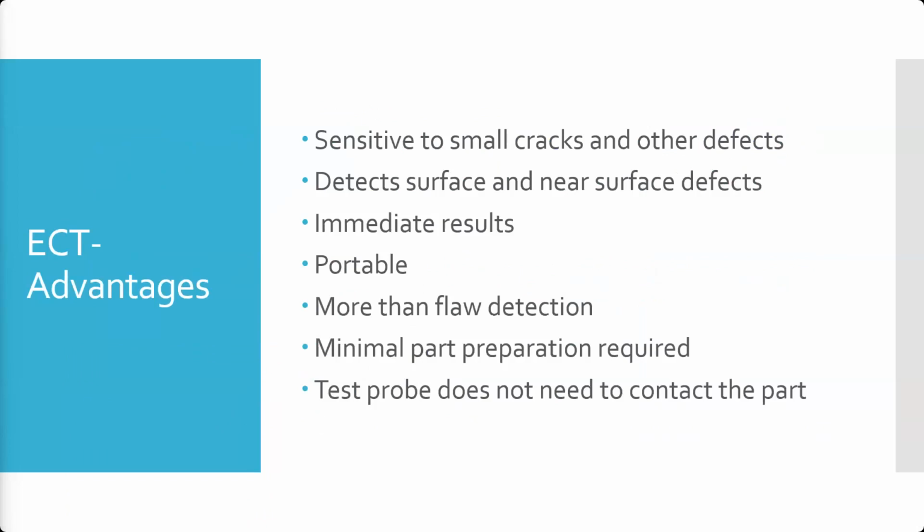Advantages are it's very sensitive to small cracks and other defects. It's extremely sensitive. It can detect surface and near surface defects. You get immediate results. You're watching the screen as you're going, and you immediately see the results. There are no dwell times, nothing like that. It's very portable. The testers nowadays are very lightweight, and you can carry them with you. There are bench versions too for doing high volume applications.